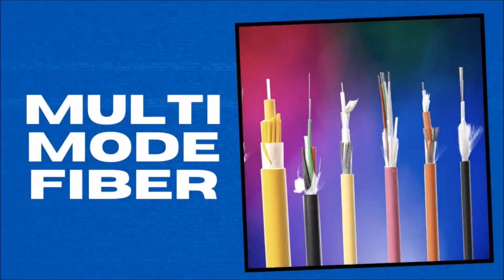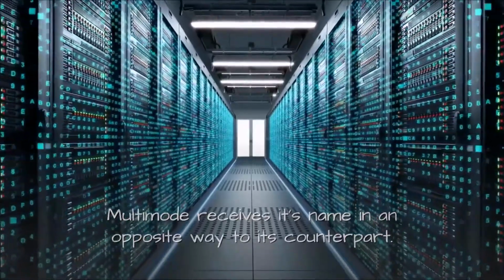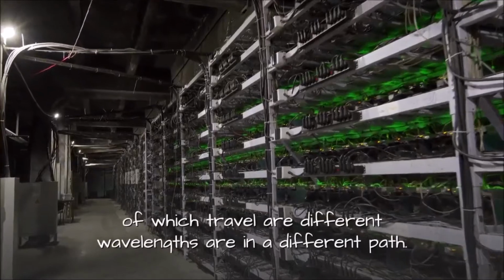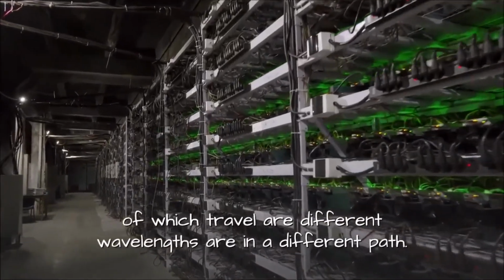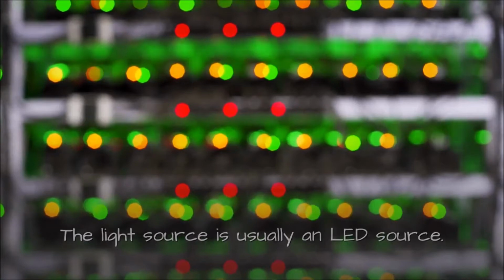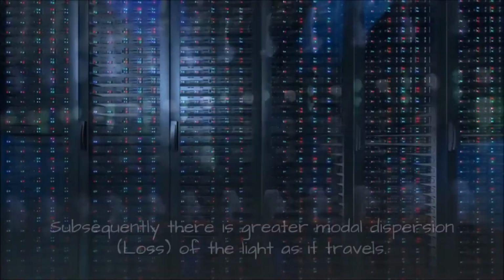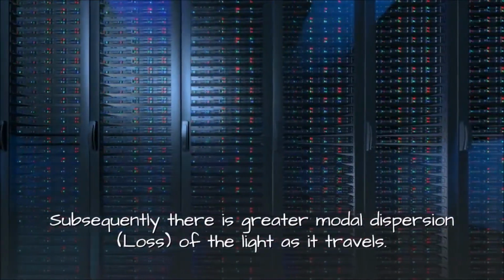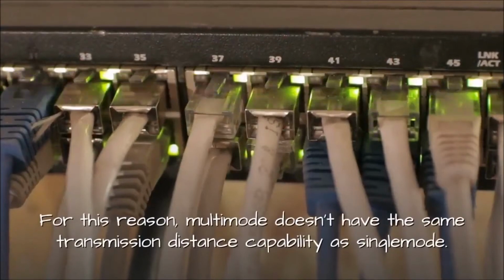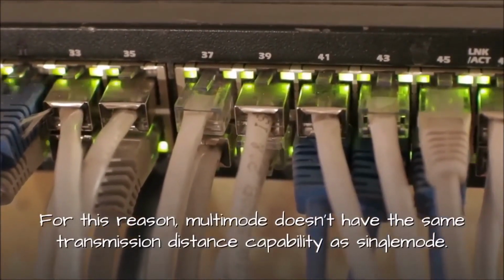Multi-mode fiber. Multi-mode receives its name in an opposite way to its counterpart. Multiple or many modes of light are transmitted down its core, all of which travel at different wavelengths or in a different path. The light source is usually an LED source. Thus the light is similar to that of shining a torch into the core. Subsequently, there is greater modal dispersion, loss, of the light as it travels. For this reason, multi-mode doesn't have the same transmission distance capability as single-mode.